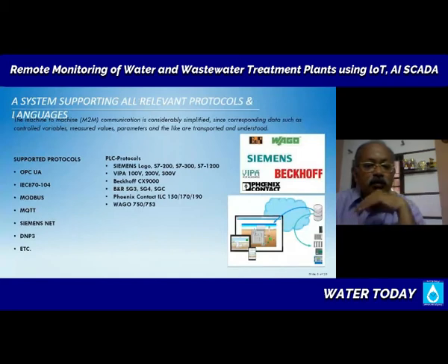And these are things that we have looked at, the communication protocol. Suffice it to say that when you are integrating a system with multiple sensors or multiple wastewater pumping stations or treatment plants, make sure that the data exchange happens through some established, proven industrial standard communication protocol. That could be any one, but it should be a standard one which multiple vendors support. Otherwise, you may end up in extreme dependency on single vendors, etc.